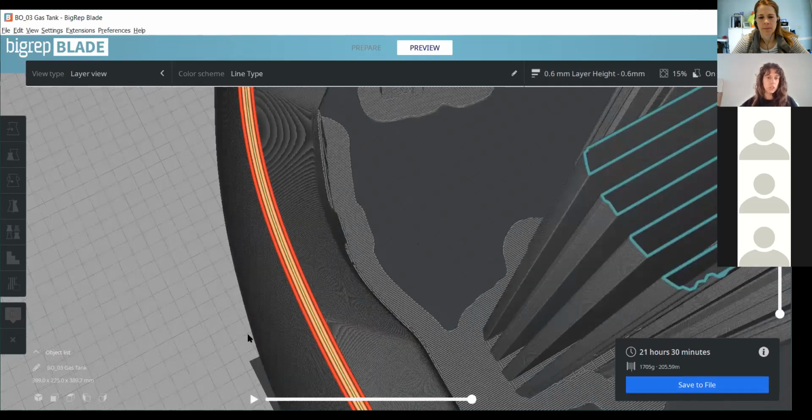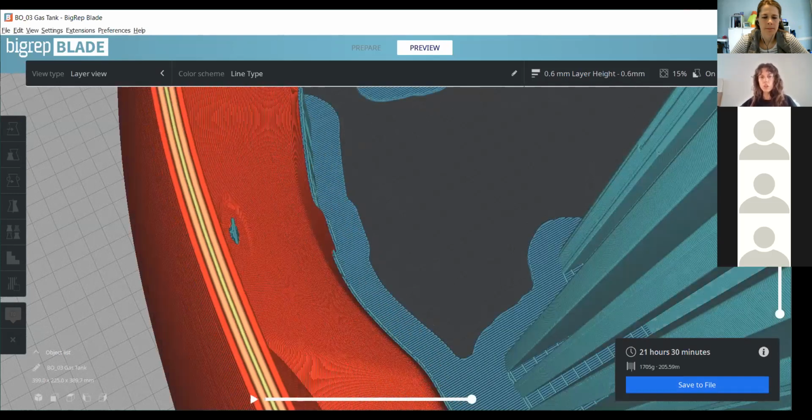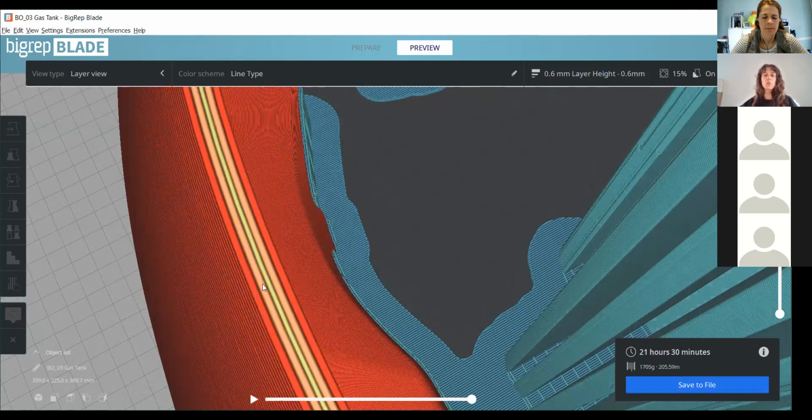See, so now actually it might have worked better before. Now that I've changed it to 1, there is a little gap there and you're seeing this yellow line. So essentially it's doing a gap fill, which adds additional retraction. So not generally something you would want. So it's all about getting it as clean as possible within the loops.